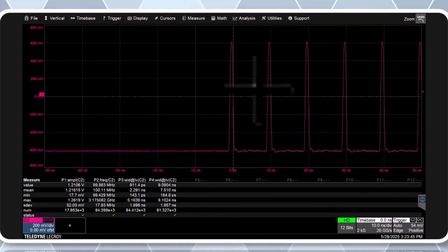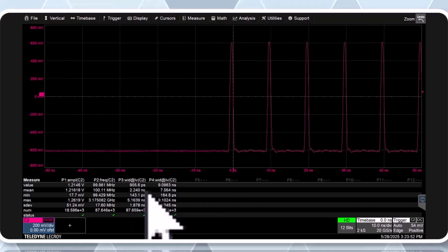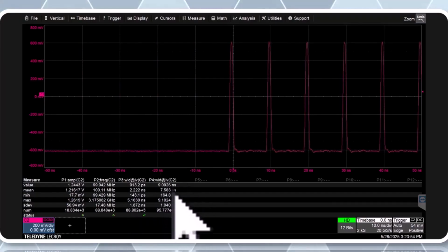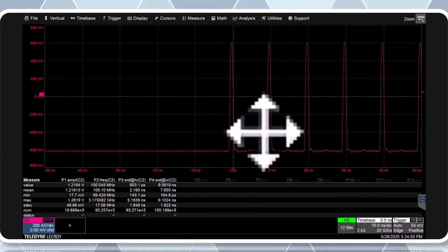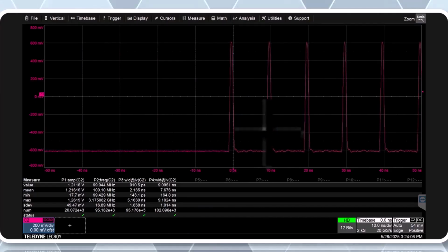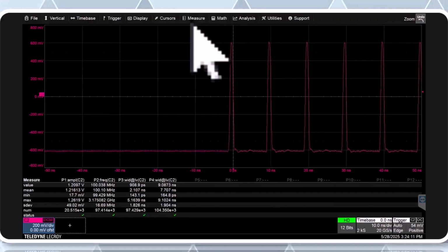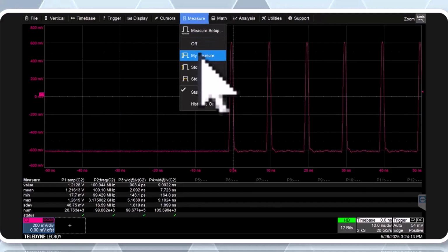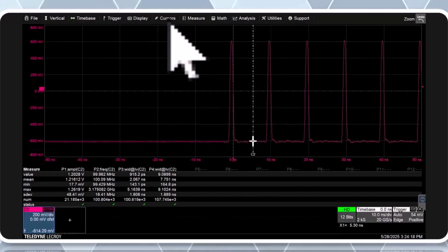And there's our pulses again on the timer. As I mentioned, we're just a little bit less than a nanosecond. This is like 900 picoseconds. However, the space between them is still, well, 9.1 almost. So the time between here and here is still 10 nanoseconds. That we can confirm with a cursor. 10 nanoseconds or 1/100 microseconds.